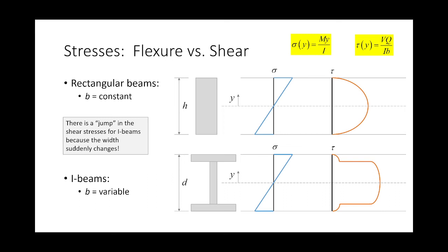Gluing them together would ensure that the transverse shear between the pages was restrained. That's what's going on in the shear diagram. That's what the shear studs connecting the concrete deck to the steel beam are doing. They are providing that transverse shear resistance.